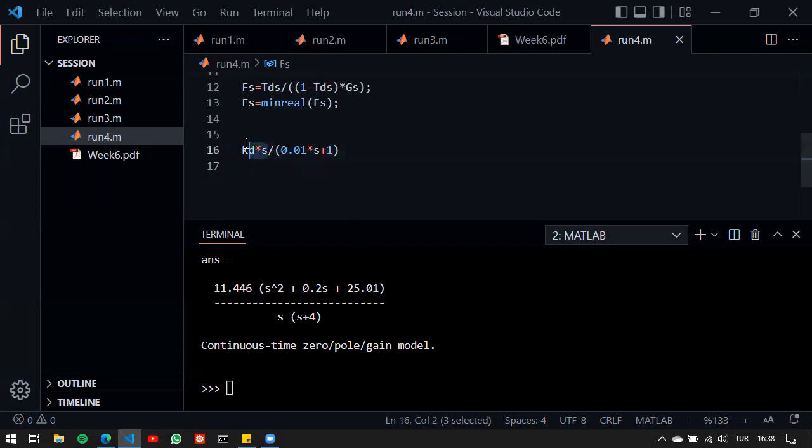And for example, the PID controller is not really that bad, because in real world applications, most of the time we don't really use the derivative directly. We use an approximation for it, or we use a filter times the derivative. So we are not really in that much trouble if we have a PID controller.